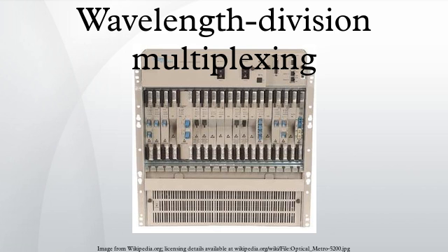These data signals are then combined together into a multi-wavelength optical signal using an optical multiplexer, for transmission over a single fiber. The terminal multiplexer may or may not also include a local transmit EDFA for power amplification of the multi-wavelength optical signal. In the mid-1990s, DWDM systems contained 4 or 8 wavelength converting transponders. By 2000 or so, commercial systems capable of carrying 128 signals were available.